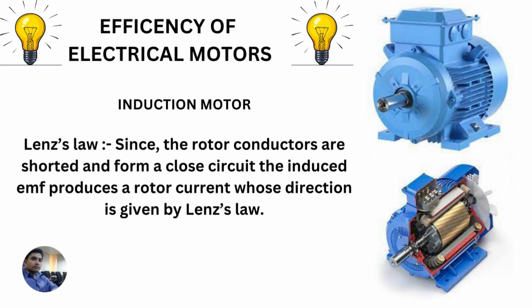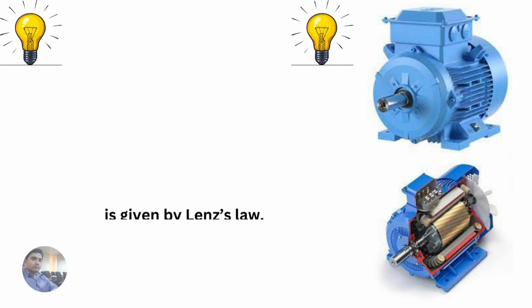And second is Lenz's law. Since the rotor conductors are shorted and form a closed circuit, the induced EMF produces a rotor current whose direction is given by Lenz's law, according to which it opposes the cause.